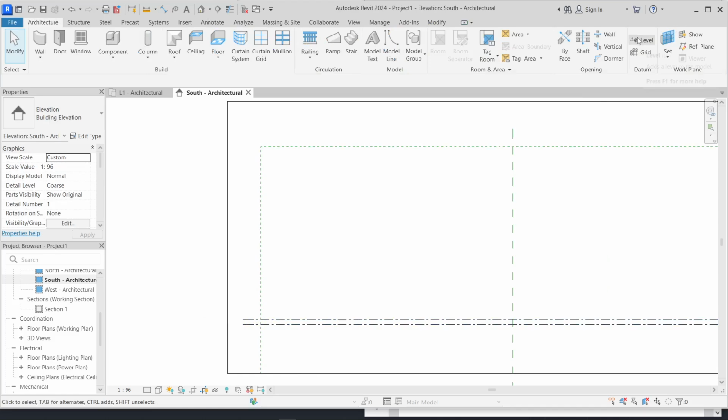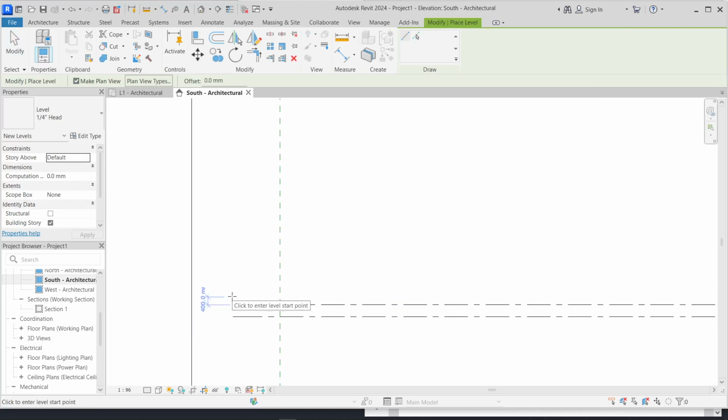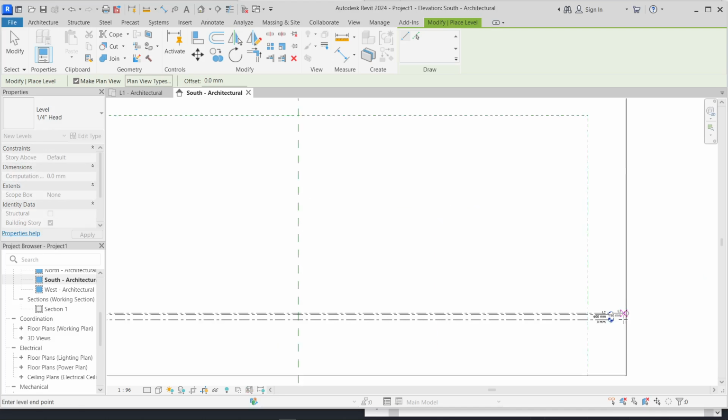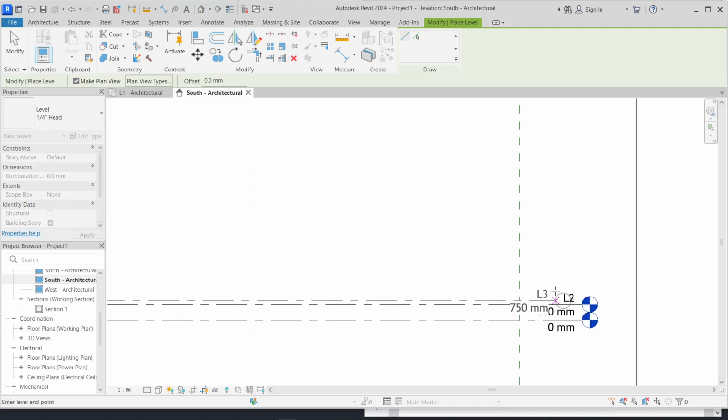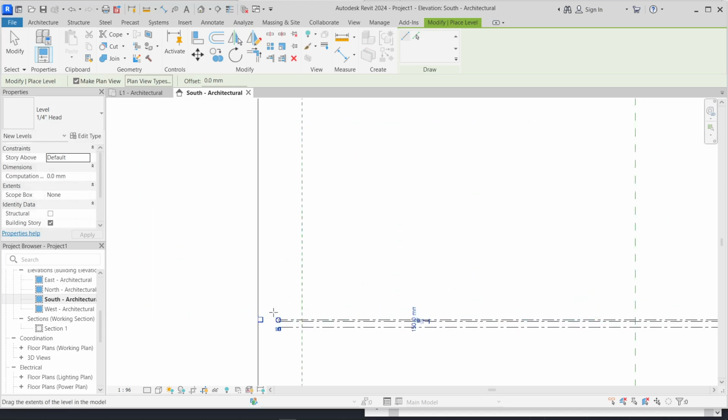How do I do that? I come up to this point, you see where they put grid. Click on this level and click on this level. Come here, identify a point. So what am I creating now? I'm going to create the space which our DPC is going to contain. What is the thickness of our DPC? I'm using 150, which is 6 inches, normal here in Nigeria. Okay, I'm dropping it.